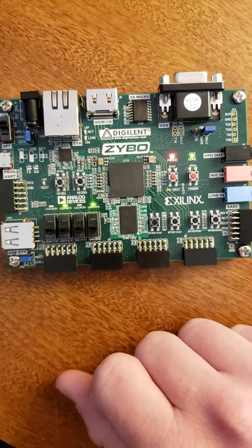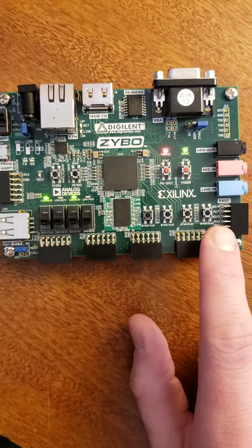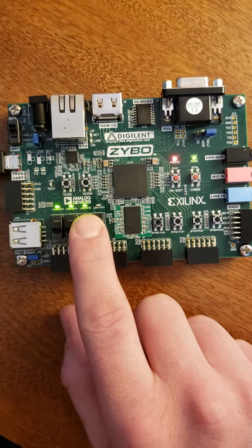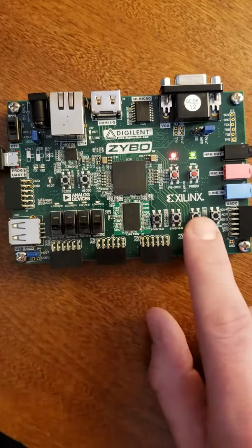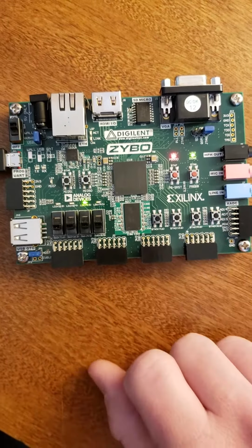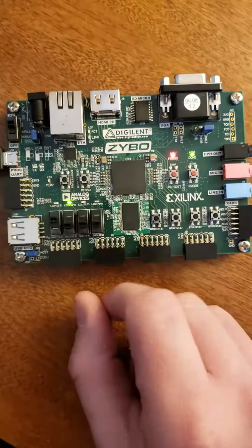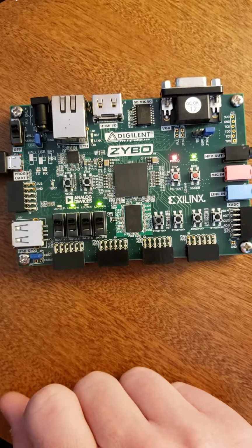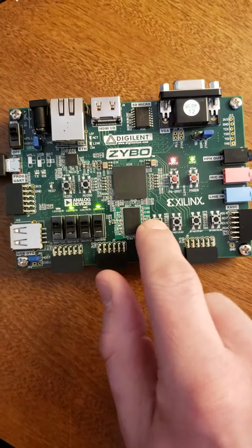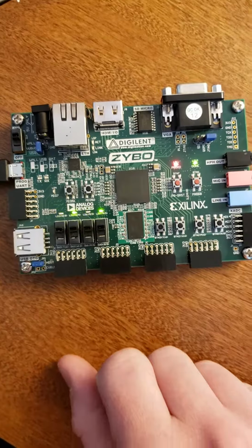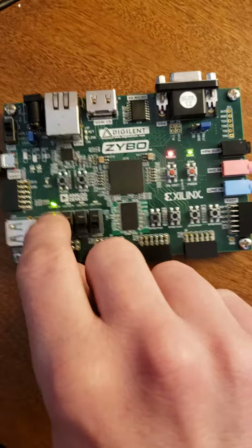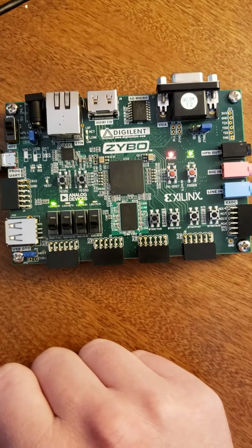And then the switches, if you flip them in a particular pattern, it locks the board. It makes it so the LEDs will blink just a locked pattern, and the buttons won't do anything. So if you flip them, switch 3, switch 1, switch 2, switch 0, it goes into the locked state, and the buttons don't do anything. And then if you flip them, switch 0, switch 2, switch 1, switch 3, it will go back to counting.